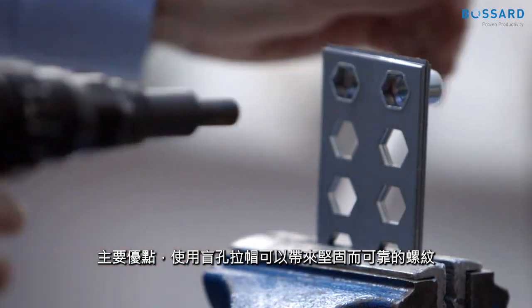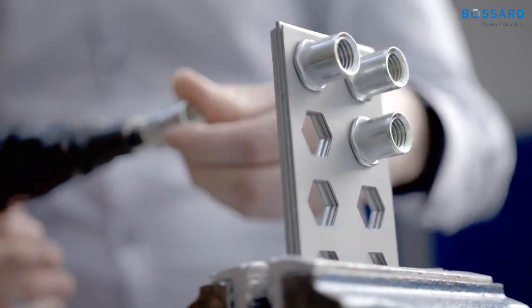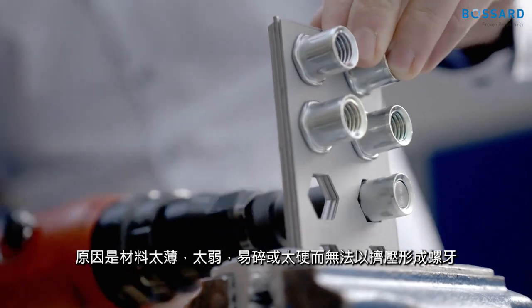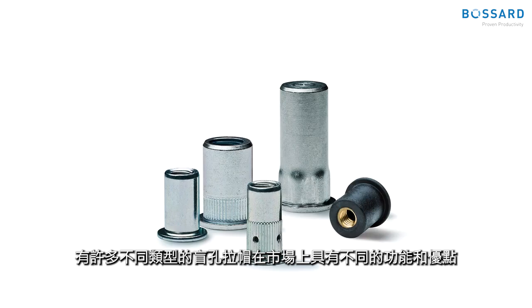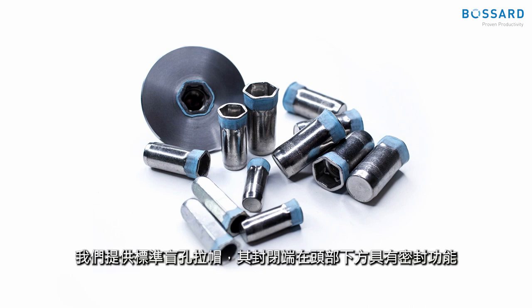But, and this is the main advantage, blind rivet nuts are used to bring a strong and reliable thread into thin or thick metal plates, profiles, composites or plastics where thread forming is either not possible because the material is too thin, weak, brittle or too hard for thread forming. There are many different types of blind rivet nuts on the market with different functions and advantages. The main types are standard rivet nuts with an open end. Or if you want to avoid water or gas leakage up to IP67, IP68, we offer standard blind rivet nuts with a closed end with a sealing under the head.